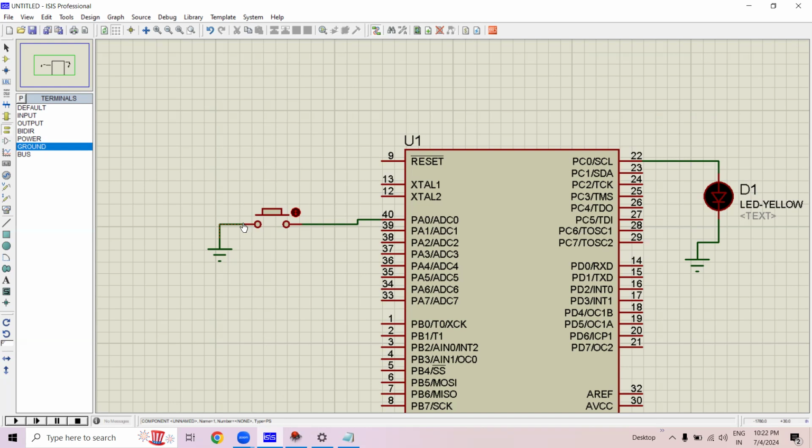So if we say like the port A0 is input and the button is providing the current to this pin, but how is the button providing this logic 1 or the current? Because button does not even have the power source connected to it. So we know whenever we connect sensors or buttons, the one end must be connected with the power source, not the ground one. So we are not allowed to use this for now. We will be using power.